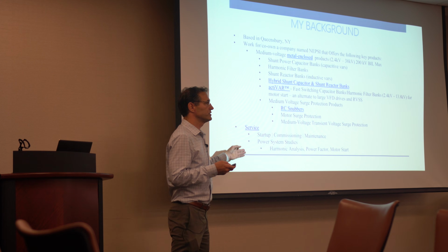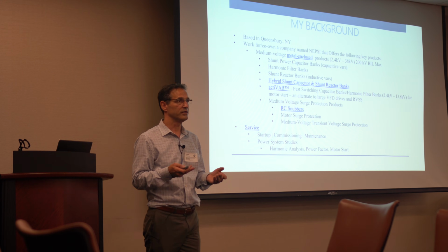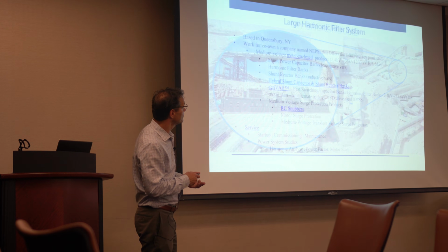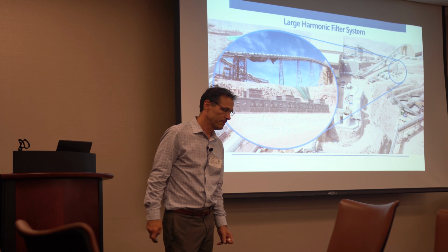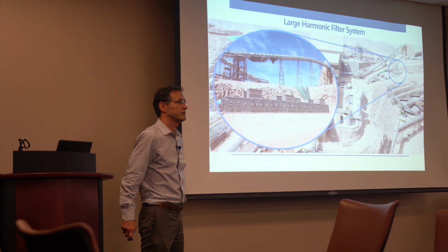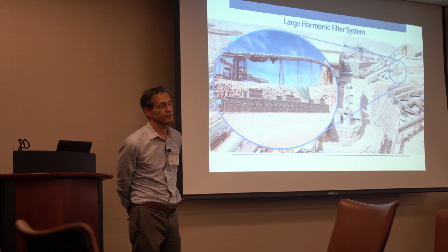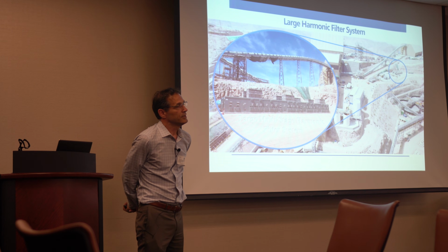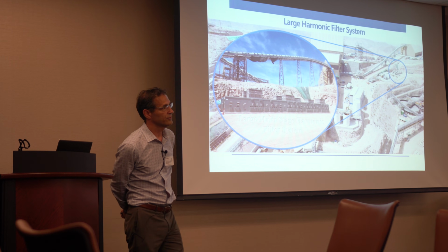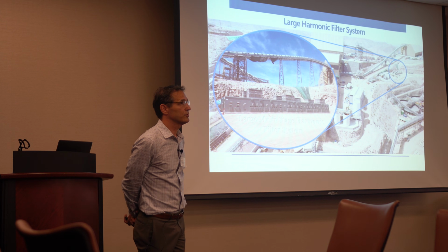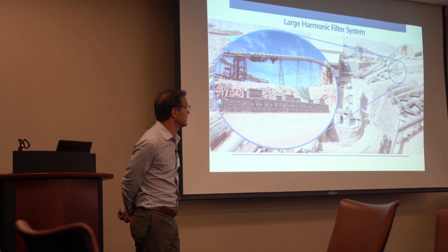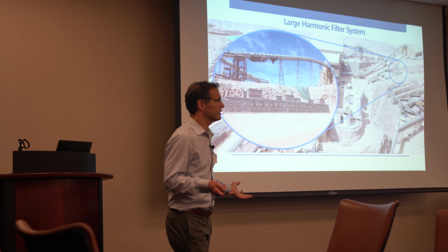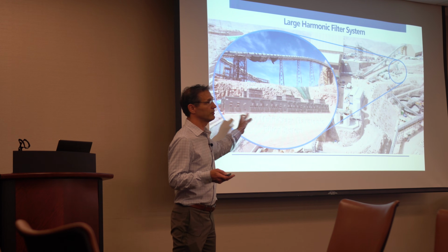And we do have smaller projects that come in where an EPC is not involved. They need some type of analysis work. We'll do that analysis. So we use a program called EasyPower, and that's an ESA software package, and it does harmonic analysis. But there's ETAP, there's SKM. They all do a harmonic analysis. They all use the same principle for their analysis purpose, the algorithms that are used inside. So this is the type of equipment we build, is harmonic filters. So today we're going to talk about harmonic analysis and to some degree harmonic filters.